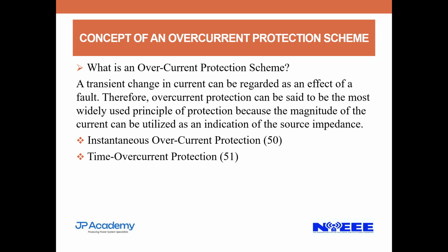Now, when this current transformer identifies that the current flowing in this circuit is actually above my set point, it translates the information to the overcurrent relay. Now, for the course of this overcurrent relay to be energized so that it can open its interlocked circuit breaker, a time margin will be considered, maybe 20 milliseconds.